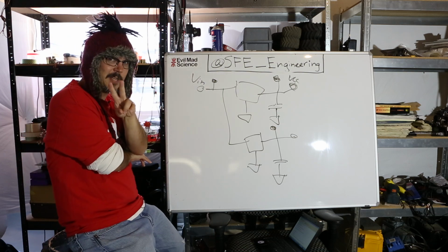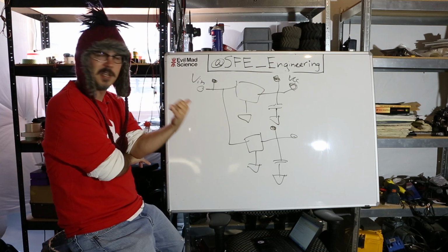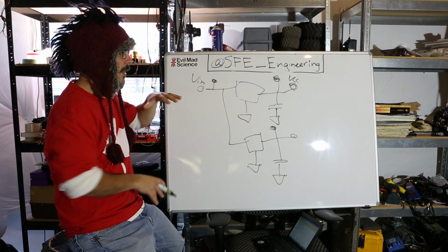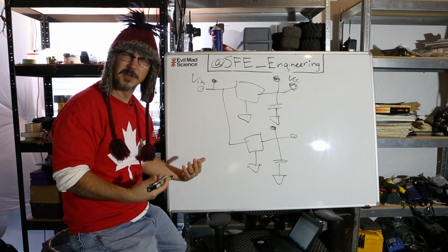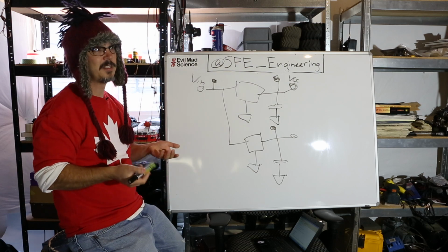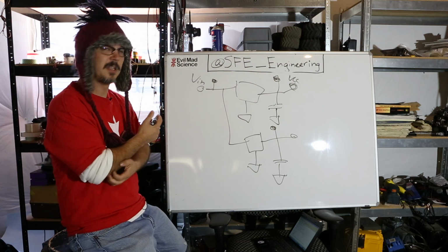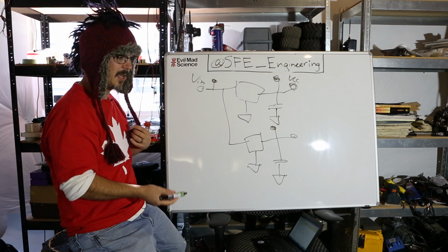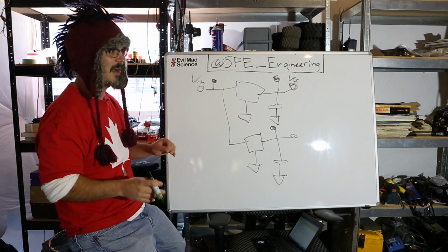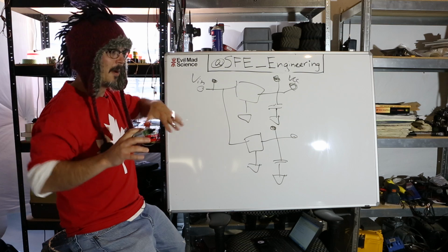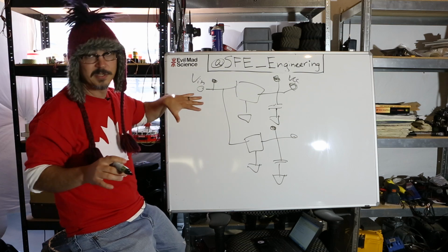There's two different kinds of testing that you might be interested in. Number one is testing a prototype, where you have to look at various points of the circuit to make sure they're working the first time. And then there is testing for production, which is a different thing. By the time you're testing in a production setting, you already know what the circuit is supposed to be doing. So you don't necessarily care about all of the bias voltages in places.